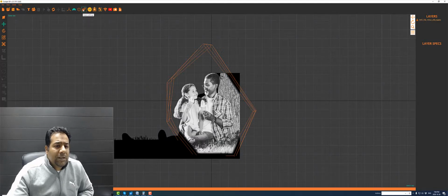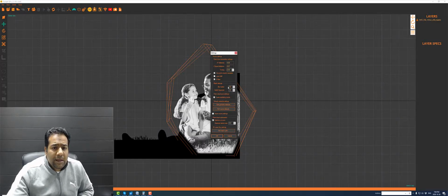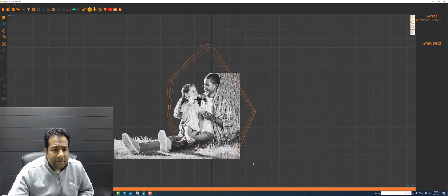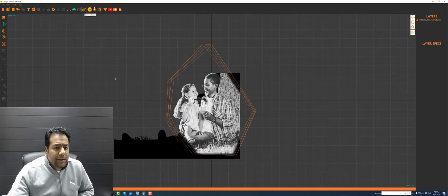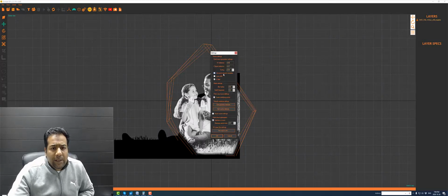The other thing that you can adjust here on that fade is your blur radius and your fall off exponent. So blur radius, think of it as almost the number of millimeters away from the edge. And fall off exponent is how quickly do you want it to fade to black. So if I make this 0, it will take its time until it fades to the black right against the edge. So watch this here. You should see a difference. We'll just let that calculate. And there you go. So it's less obvious than before. All right, trim point cloud template we talked about.